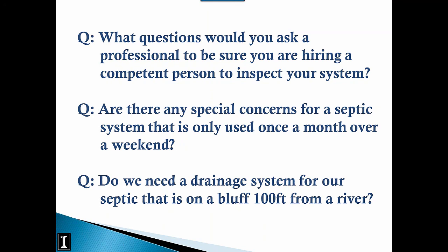Nothing's corroding, nothing's leaking. The seals going into the septic tank aren't leaking, which you don't want, an inflow of groundwater in times of rain. You want the tank to be completely watertight until it gets to the leach field area. So definitely check out those references before, and then once they're there and they're doing the inspection, make sure they're opening up every part of that septic system, make sure that they're getting a good look inside.